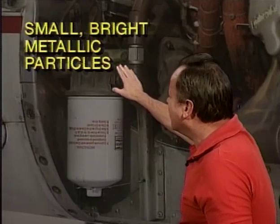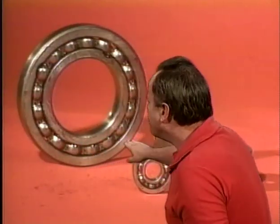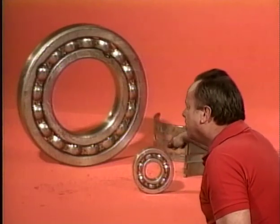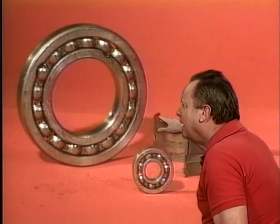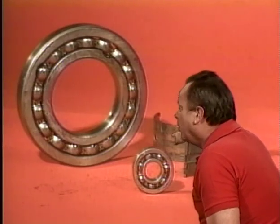What does it mean if they're not magnetic? Well, it tells you that it's not iron. So where could you get this? Well, it could be the result of abnormal plain-type bearing wear. Here's plain-type bearings over here. And if you have abnormal plain-type bearing wear, they are normally, of course, not made out of iron. And, of course, that kind of metal in there would be cause for further investigation.